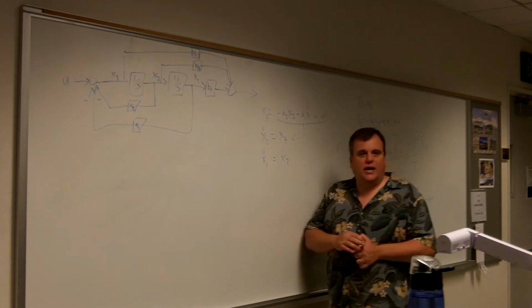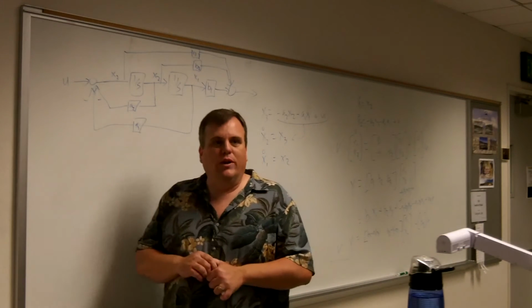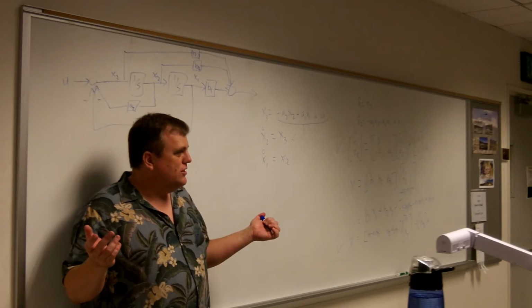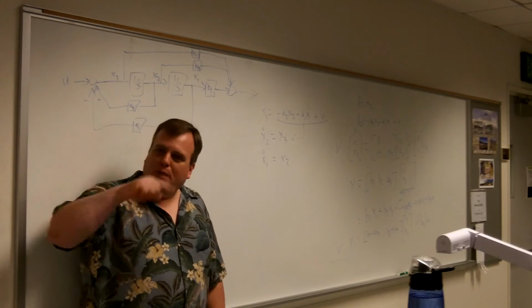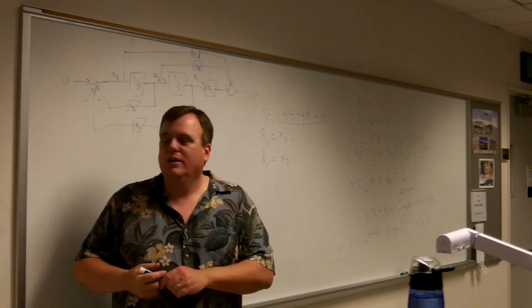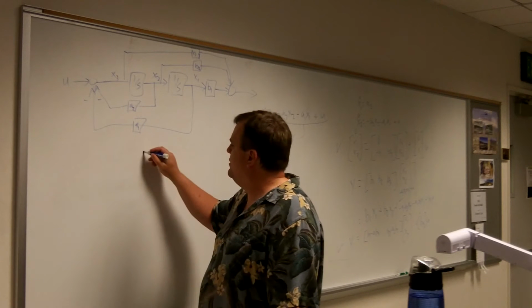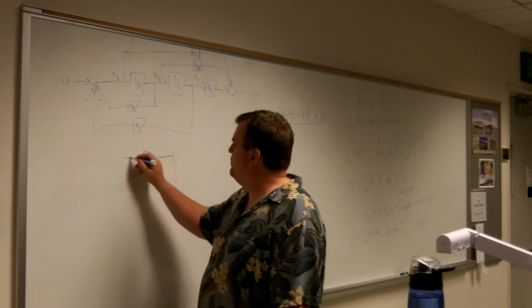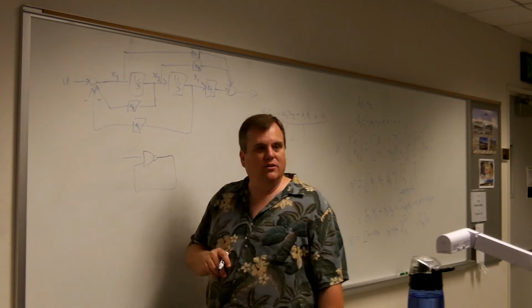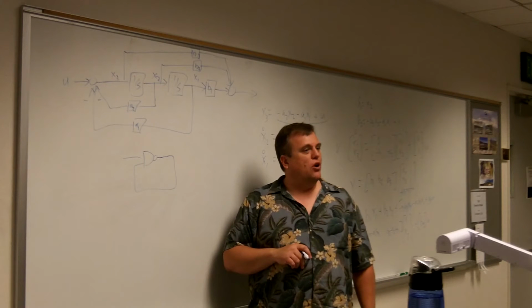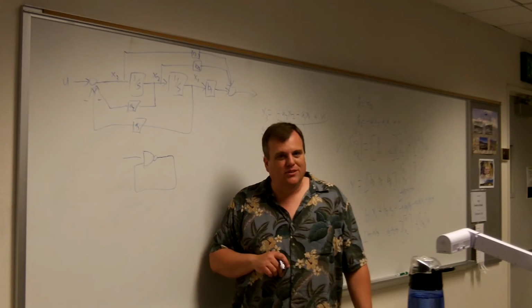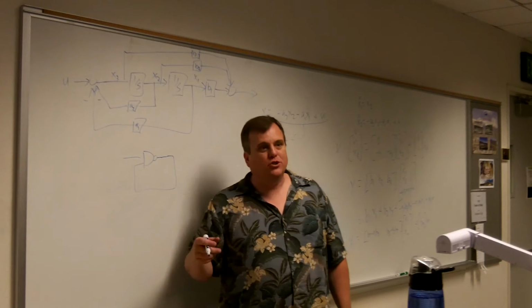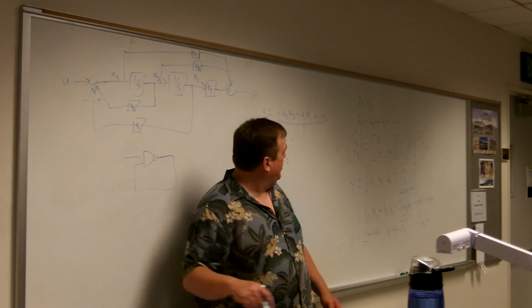Everybody's had digital logic, right? We got these things we called states, inside of digital logic, your 310 course. And when you did feedback, if you fed back the output of something, like say I took a NAND gate and I fed it back into itself, I could get memory, couldn't I? And that memory we called the state of the system. It's not an accident. Every feedback loop gives you state. It's no different here than it is there.